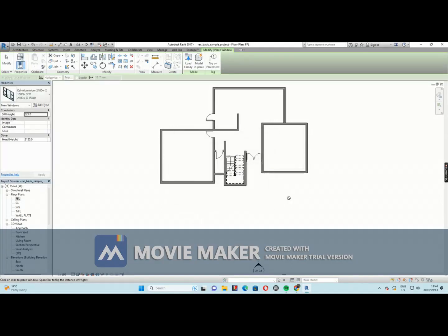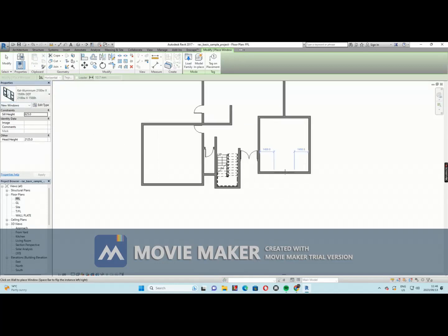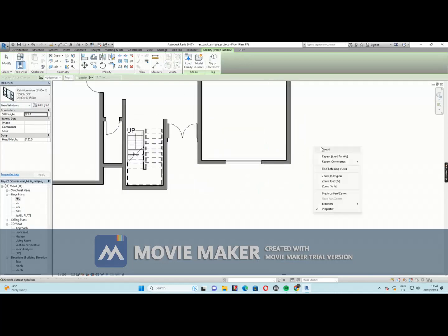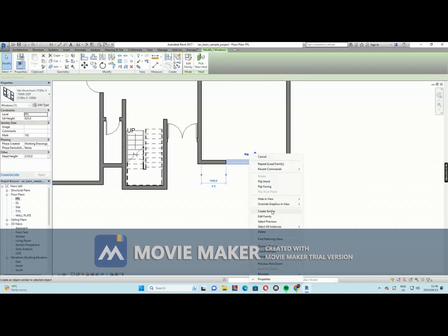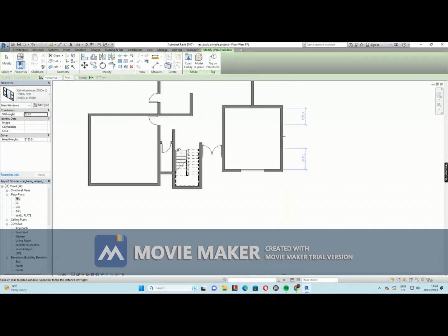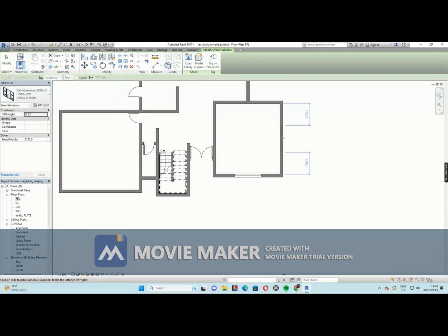So for this big window, I can put it here. You see? If you want to center, normally Revit, when you have a window, it will center for you. The more you shift, the more you get your center. You see now it's 1700, 1700, all. So you have to center. But let's say you just randomly put it, but you want to center it.